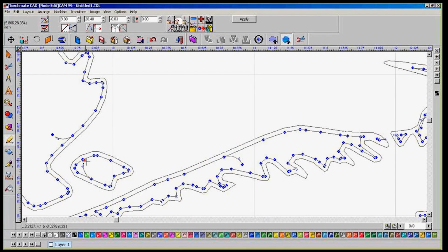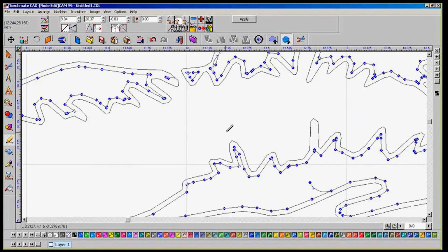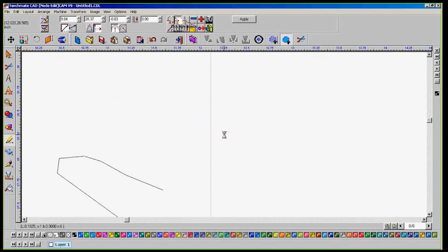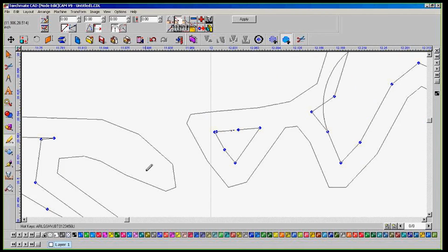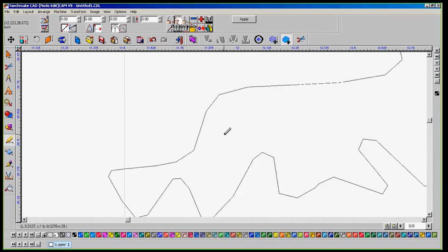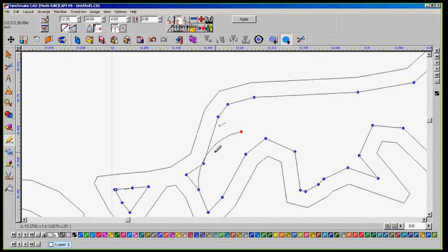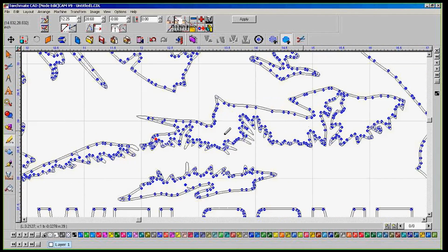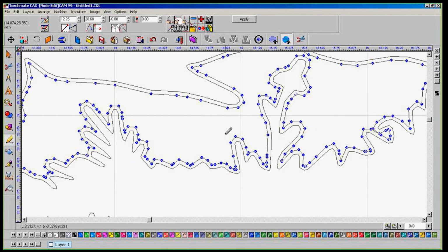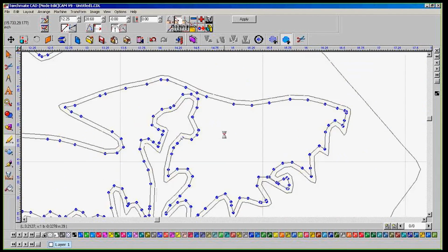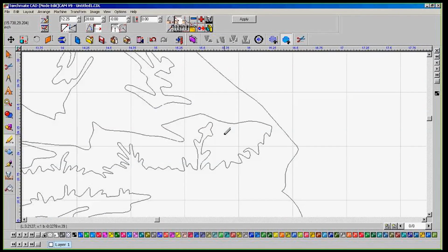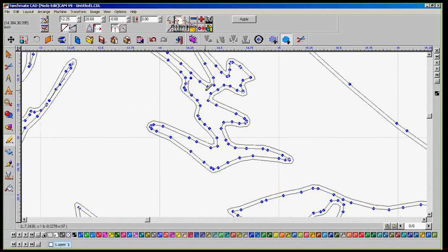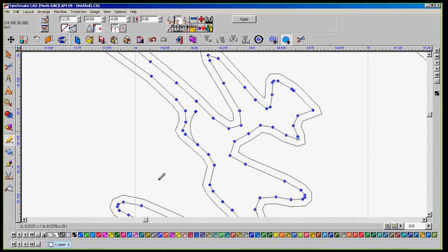So how I do that is I select everything, Control A, or you could draw a box around it, and go to Layout, Sequence, and then Start Sequence by List. Now what this list shows you is it shows you your drawing, and it also shows you the tool itself. So I'm going to select Tool Path only, because that's really all I need to worry about. As we can see, once you have this item selected, it shows you in the design where that is selected. And we want to make sure that this item here is sent to front.